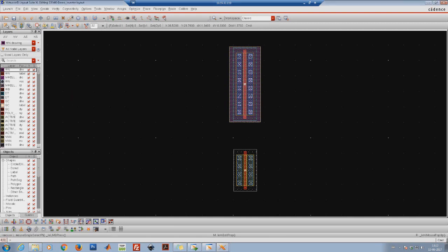This is because this tool generally remembers whatever the last width that I have set in the schematic. That's why by default the size of this PMOS is 4 micrometer. Now I have placed both the transistors.